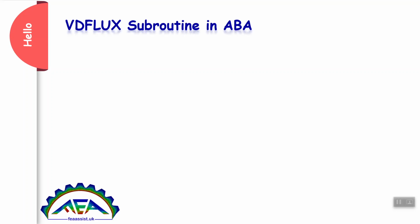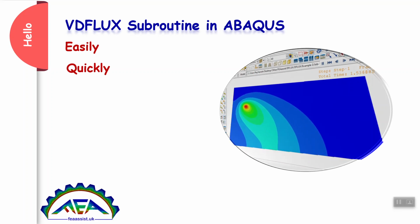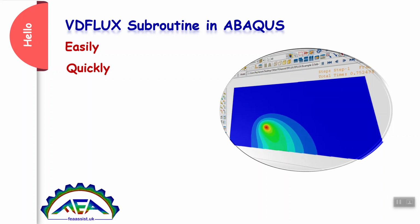Hello, you want to learn the VDFlux subroutine in Abaqus easily and quickly. Actually, VDFlux is a subroutine to have a movable heat source on your plate or on your sample, which is used in some processes like welding or additive manufacturing.